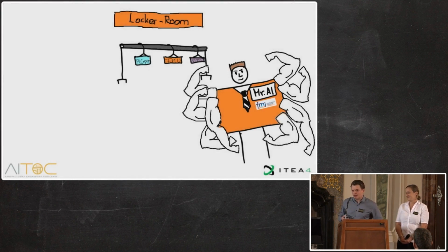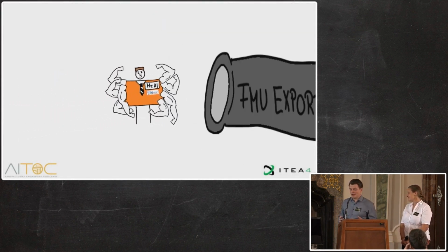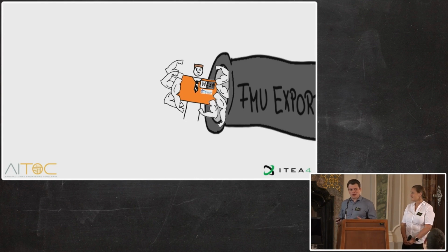In the next part you have to export this FMI AI model in a proper way. We have trained it, for example, with TensorFlow. You have your TensorFlow model, which is executable with TensorFlow, and here you can use the FMI standard as an interface. The FMI standard will surround this model, and our environment can execute it. The FMU is really close, but it has inside all the dependencies it needs for execution of a TensorFlow model, for example. This is the main work of the FMU exporter.